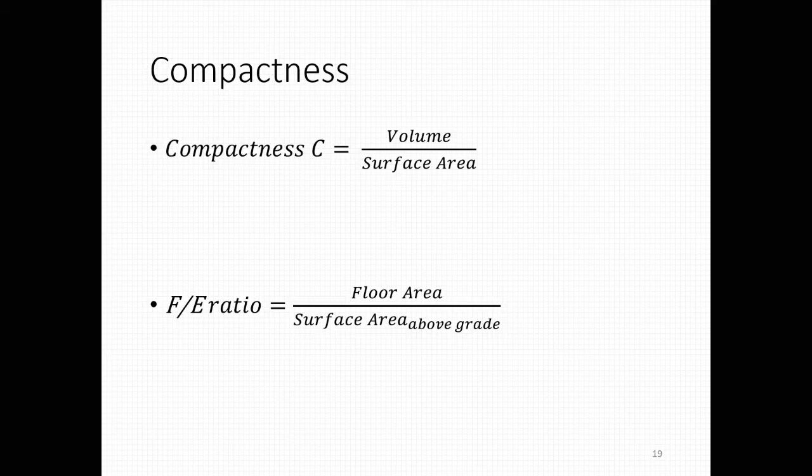Remember, all of your surface area above grade, and even below grade, though it's more true above grade, has those delta T's driving the heat transfer across your envelope. We have to spend money to control that heat transfer and keep our building comfortable.